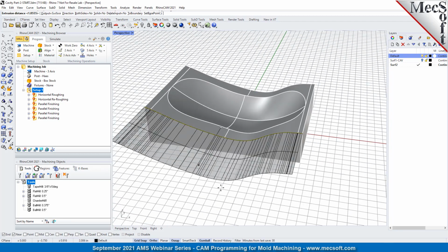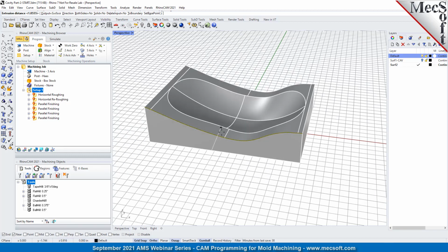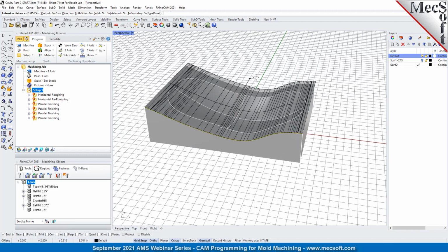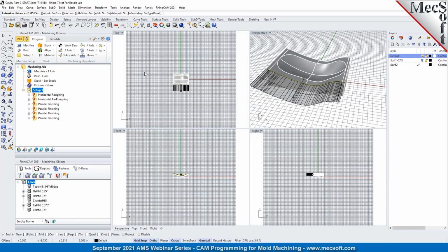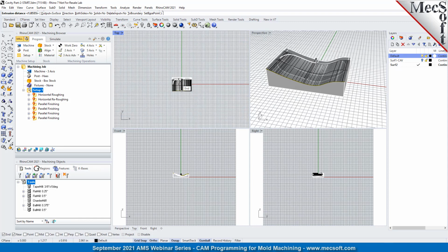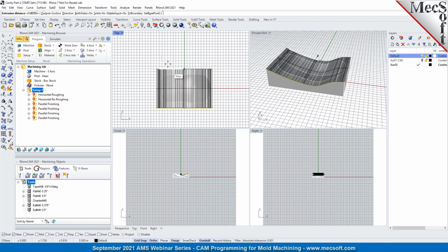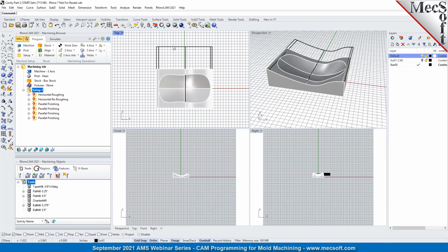We're going to right click, and you'll see that it's extruding in the default direction of the parting surface. We don't need to know exactly how far it's going to overlap. We just need to make sure that it's at least half of the tool radius. So we're going to bring it over a little excess. You see that you can see through the surface.